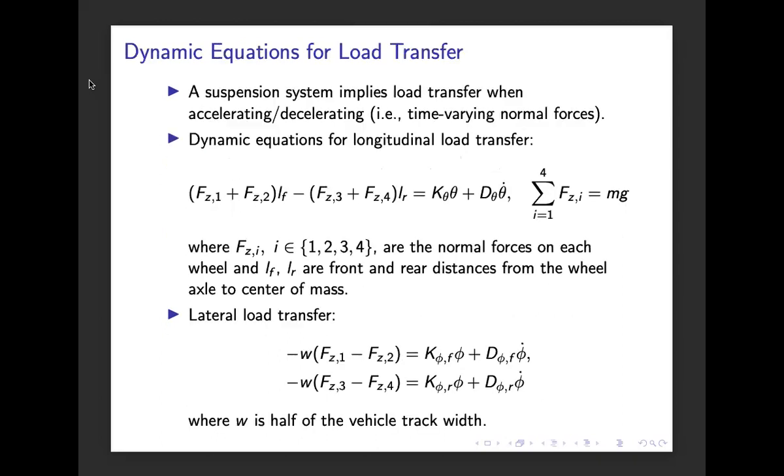And the suspension system implies that we have a load transfer when accelerating, decelerating, or even cornering with the vehicle. So it means that we will have time-varying normal forces. And if we are using a differential algebraic equation based modeling approach, it's quite convenient, because then we can introduce differential algebraic equations stating that the sum of the normal forces needs to equal the total gravity on the vehicle.